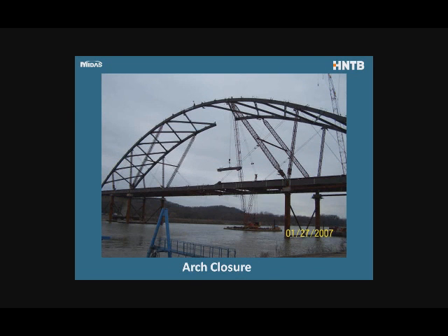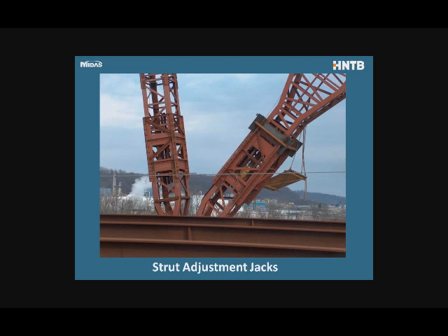Now the arch rib, the keystone segments for the arch rib, this is where it gets really interesting because they cannot really push anything apart anymore. But what you can do with these struts is to actually shape the opening by moving the struts up and down, and that was pretty amazing. The strut system.